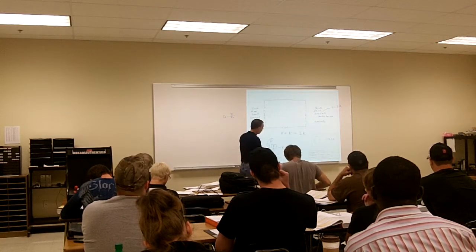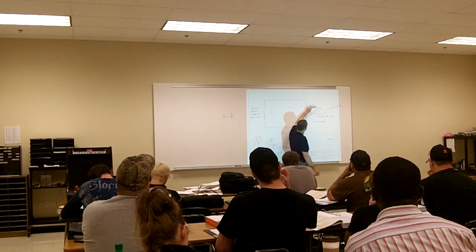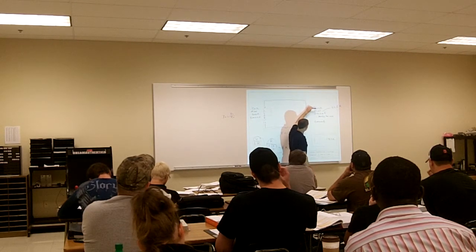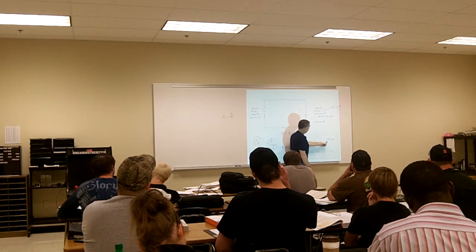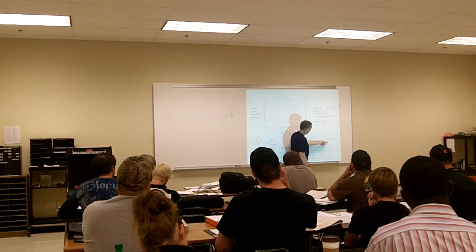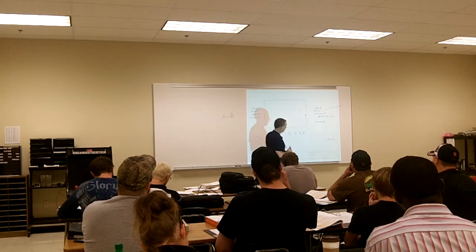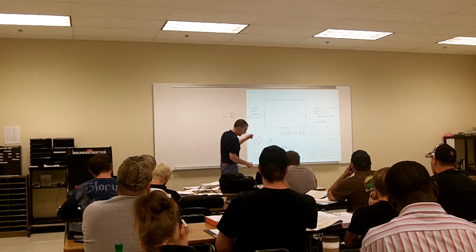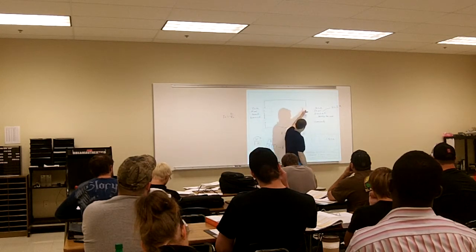So that's the value of that resistor. The color code says it's supposed to be 120 ohms. We use that for our approximations. We always use the color code for our approximations. We want to measure it to make sure that it's in tolerance, and it actually turned out to be 118.5 ohms. So I go ahead and throw that 118.5 ohms into my circuit.